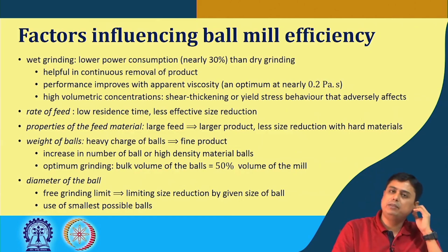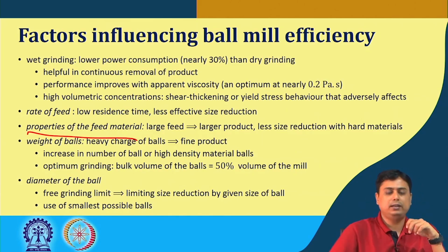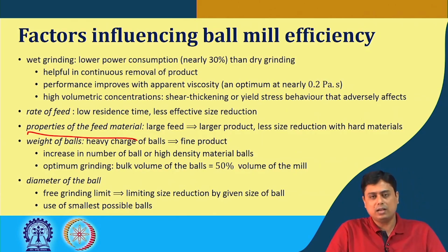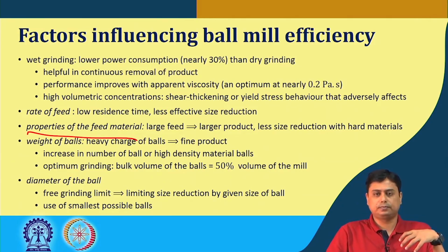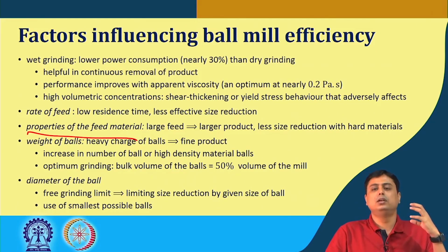The properties of the feed material is another important factor. If you use large feed, there will be a coarser product. Less size reduction of the hard materials can be achieved if you use hard materials. So, the quality of the feed is important.